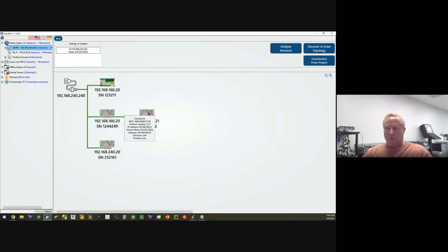The exception now comes when you have a lot of cards. So let's say there's 3 cards, and there's another card right here. You initiate auto configure. Before it will even begin, the first thing that this new card does, it'll say .20, what's your configuration ID number? It'll say .22, what is your configuration ID number? And if they don't match, it will abort the process, because the new card does not know which card on the conveyor actually has the correct information.